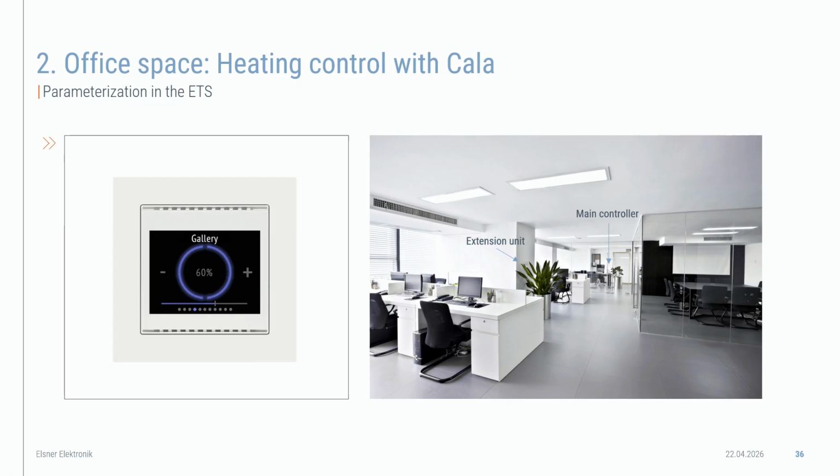Also, an additional important feature is that in such large rooms, you can have different temperatures within the room, so it's not very uniform. For this reason, we could use the temperature from this extension unit and mix this temperature value with the main temperature recorded on the other side of the room, and thus we will have a more uniform, homogeneous average value.